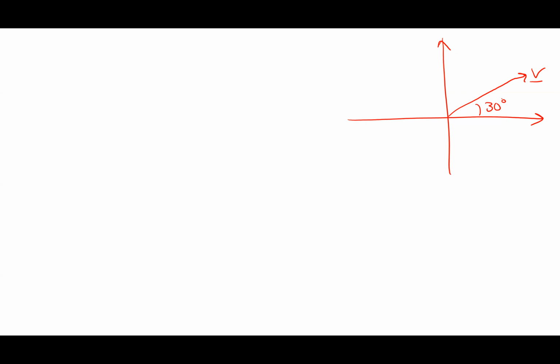How can I figure that out? The phase of Z is equal to the phase of V minus the phase of I. Yeah, so knowing that I know the impedance angle right now, I could get to the angle pretty quickly. There's a couple of ways I could do this. I have that the magnitude of S is equal to VRMS times IRMS.